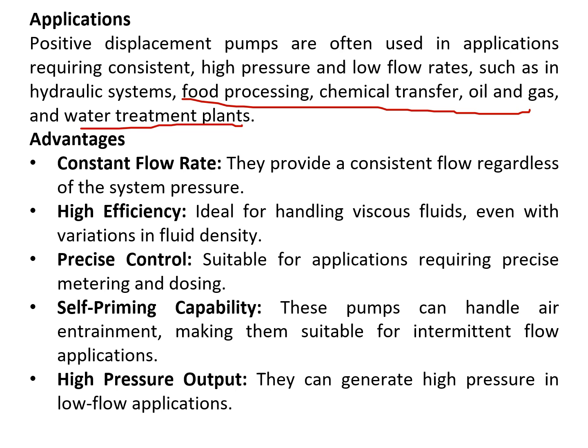It achieves a constant flow rate and precise control, self-priming capability, and high pressure output. Self-priming capability is the most important one, because in some cases priming needs to be done to operate the pump properly. Self-priming capability is there for positive displacement as it creates its own vacuum. The pressure output is very high compared to other pumps.